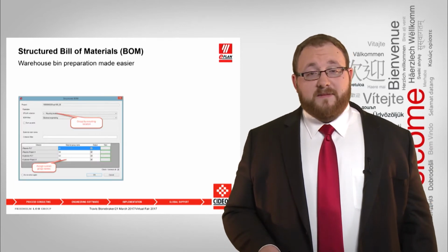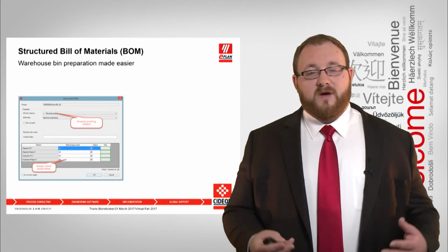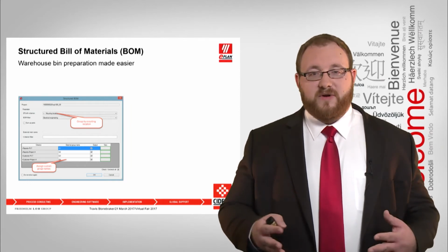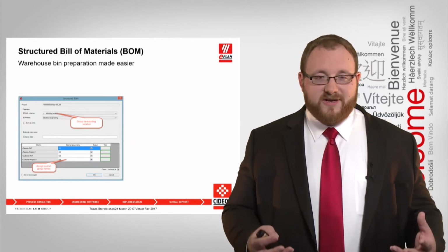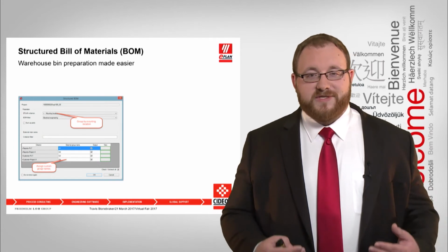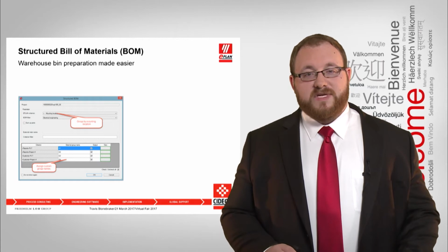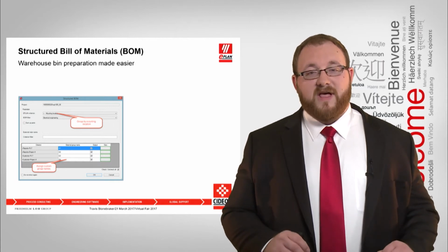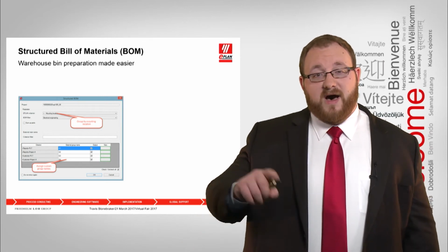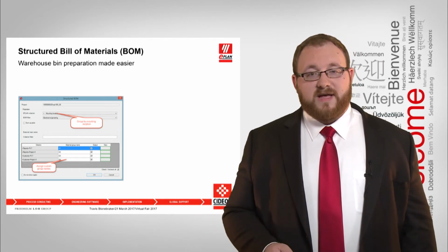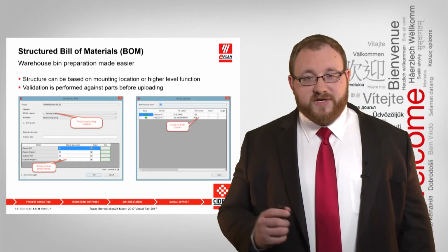Now, the last couple topics I want to discuss is this structured bill of material. So for the IT-minded, when you actually build a bill of material, which is shown here, you have this view where you have these Eplan criterion and also the BOM filters that you can select with this menu option. Down below, you see the different levels within the Eplan project, and then on the right-hand side, you see a green box. This green box, when you select it, brings open this other screenshot here.